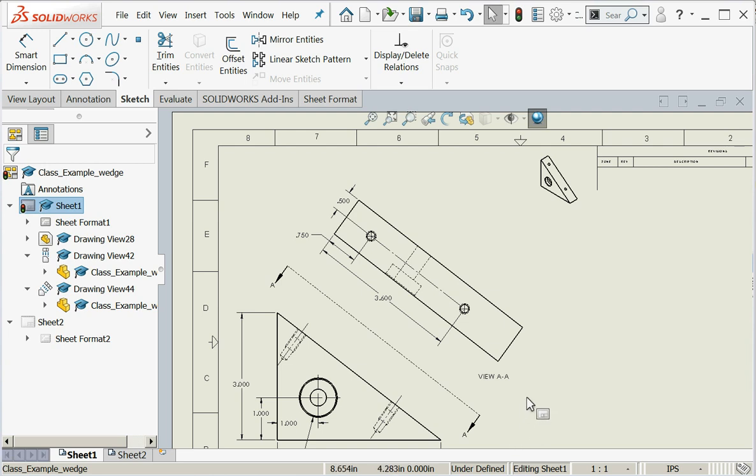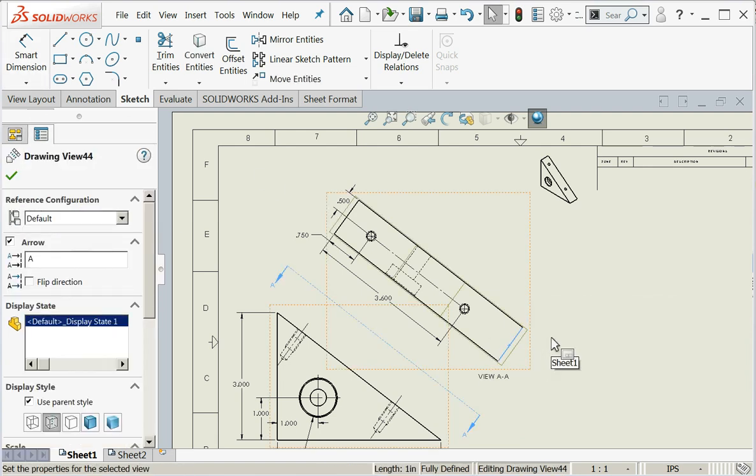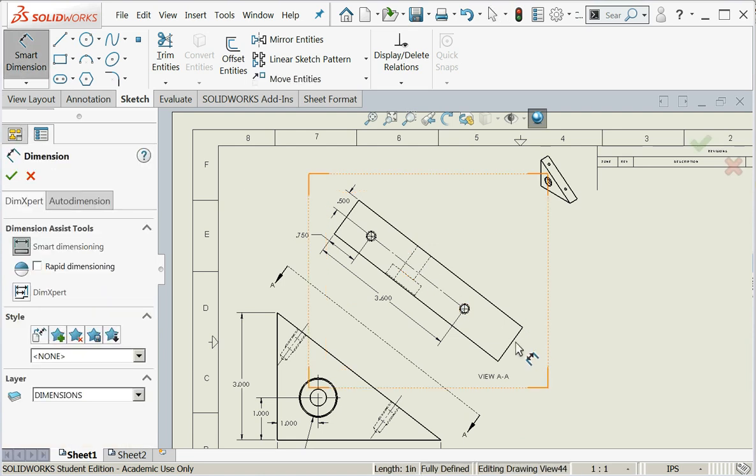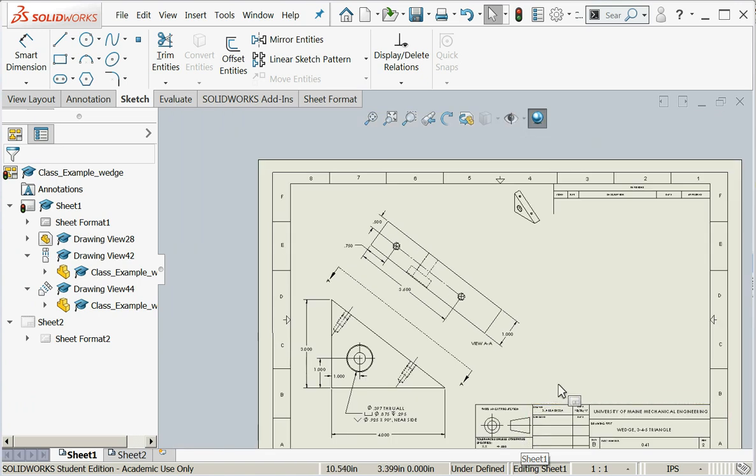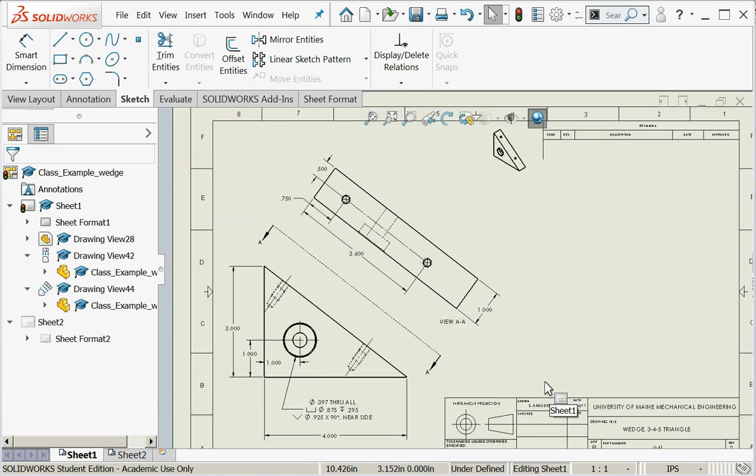Okay, so I'm missing my material thickness. I need to put that back on from deleting the previous view. Whoops. There we go. So let's see how we've done. I have the height, I have the width, I have the thickness. So that tells me how big a block of material I need. I've located the counterbore hole. I've specified the counterbore hole. I've located these two holes.